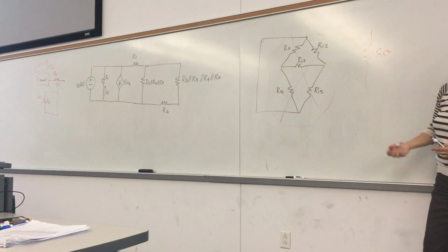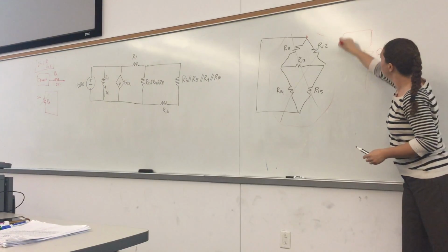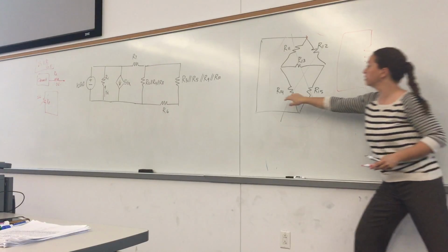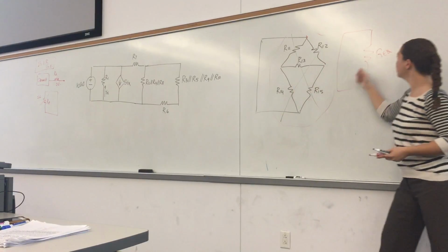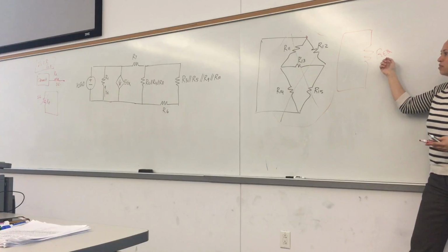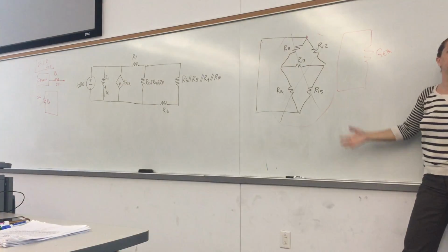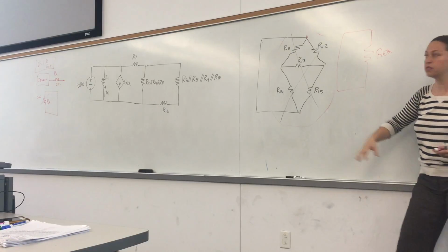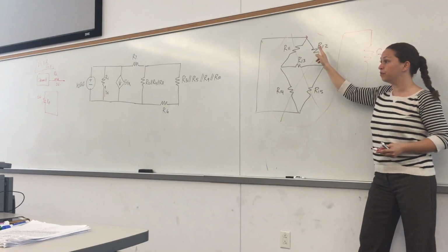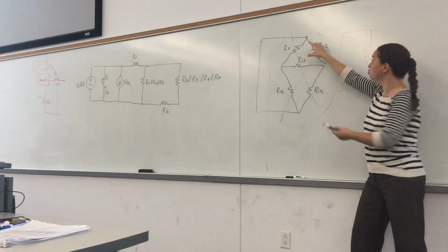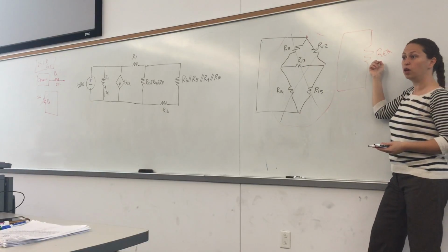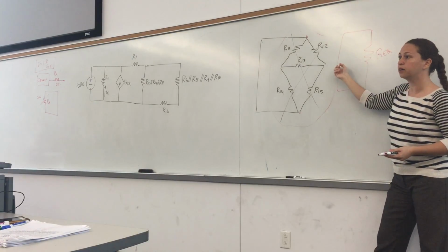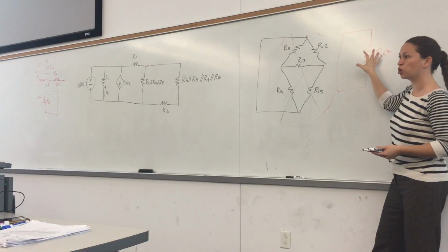And this equivalent resistor would be what? In parallel with this wire here. And then what? That's going to be shorted. Do I care about this value? If it is R1 in parallel with R12, then it doesn't matter. All that matters is that it's purely resistive, which will come down to a single equivalent resistor, which will be in parallel with a wire. So it's going to be irrelevant to the solution.